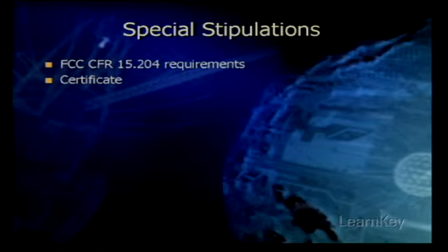Understanding this requirement becomes especially crucial when you're dealing with amplifiers, because a system is defined as the transmitting device, the cabling, connectors, amplifiers, attenuators, splitters, and the antenna itself. And manufacturers obtain FCC approval or certification of their hardware such that an end user may purchase any of their radio devices and antennas and use them as a system without having to contact the FCC additionally for testing and certification.